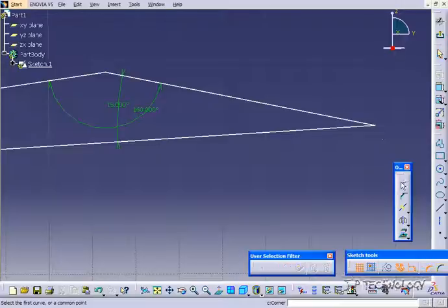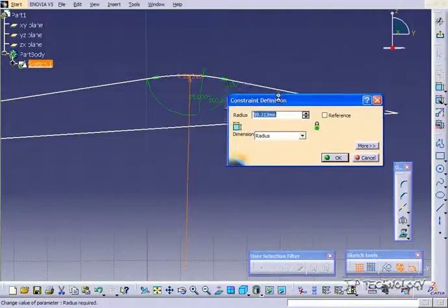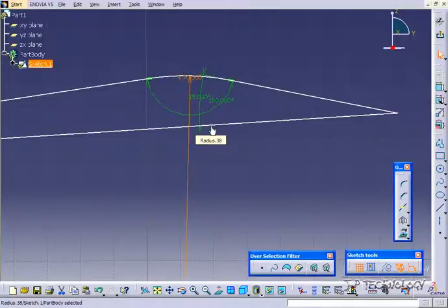So if you click the corner, the first one, let's do this larger one here on the 160. So we'll click this line here and this line here, and you're able to see that we're able to pull it and it comes down, and with a larger opening or a larger angle, it takes a lot more to create that curve in it. So you're given a lot of leeway when you pull it down. So let's pull it to about here, and you'll see that the rad is about 60, so let's put it to about 70. Click OK, and there's not too much change.